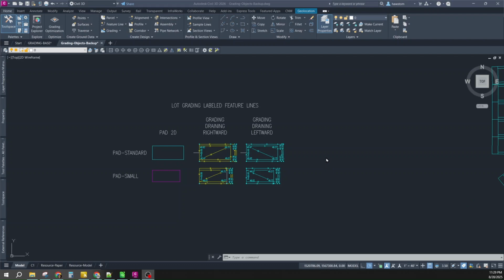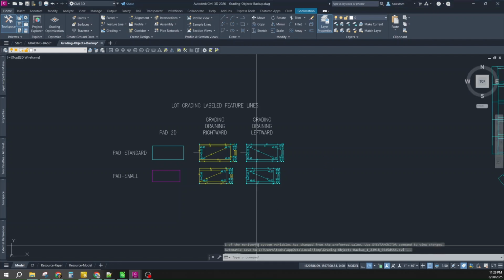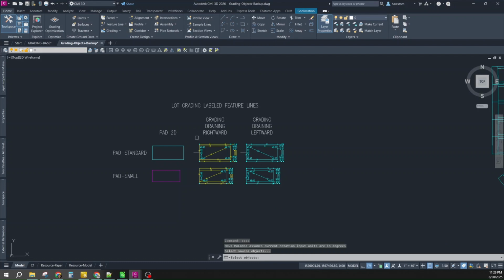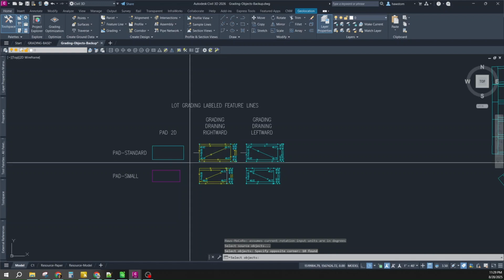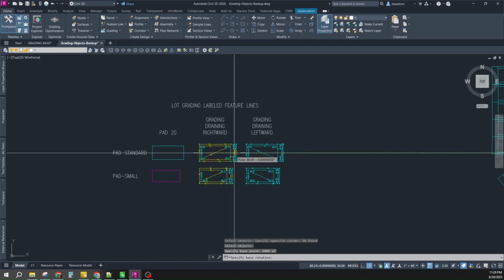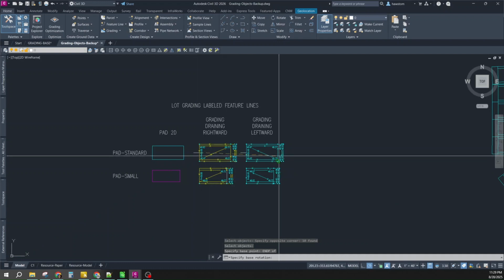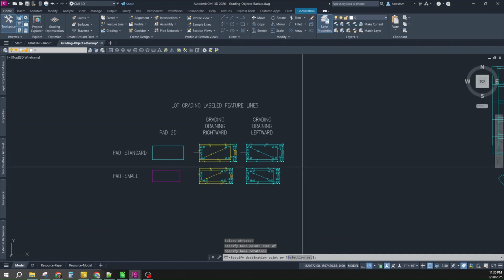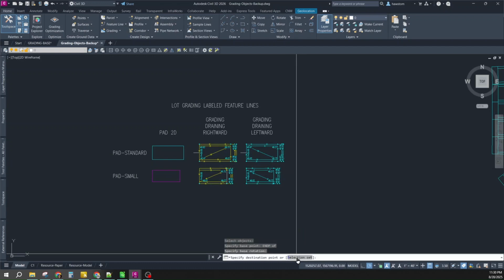The nickname we came up with for Haws-MoCoRo was CCCC. So I'll type that, then I'll pick my feature line pad grading objects. I'll pick the base point that matches my pad block on all the lots, which is the front middle, the rotation that matches them, and then I'll say copy all that to a selection set.